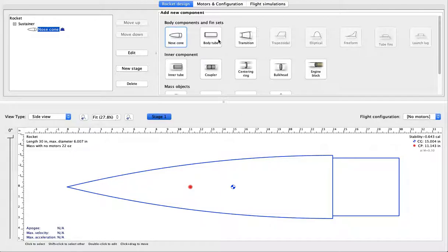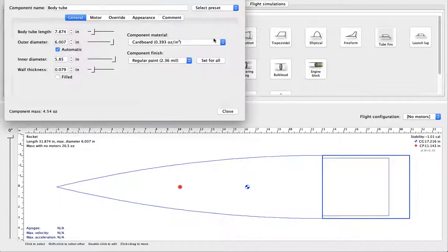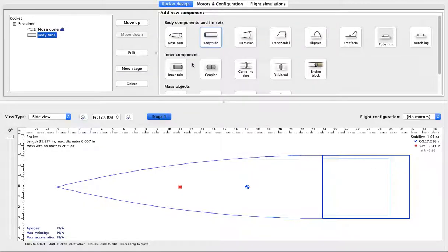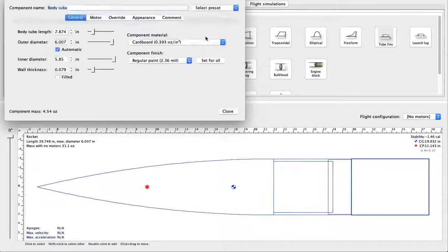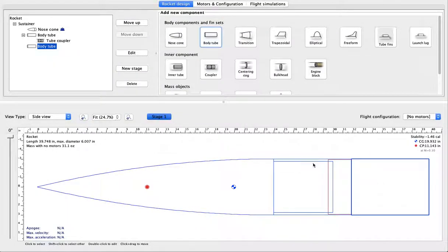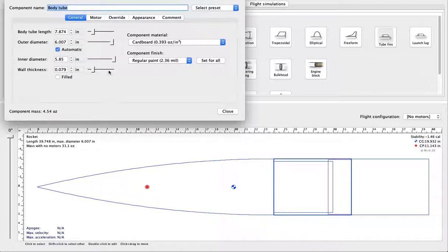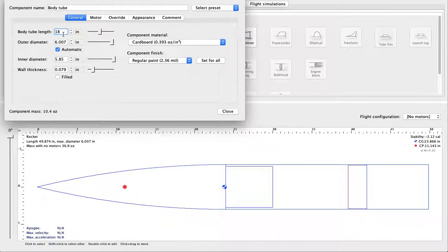To separate your rocket, you need to separate for your parachutes to deploy. Usually we build our rockets like this. We'll have one smaller tube, we'll have a coupler, another tube, and then we'll add fins to this tube. So let's start putting in some normal lengths. We're not just shooting a little bullet. So first of all, we can call this something like 18 inches. I know my team rolls our own tubes. So we can adjust this as we go, but many people will buy these tubes.